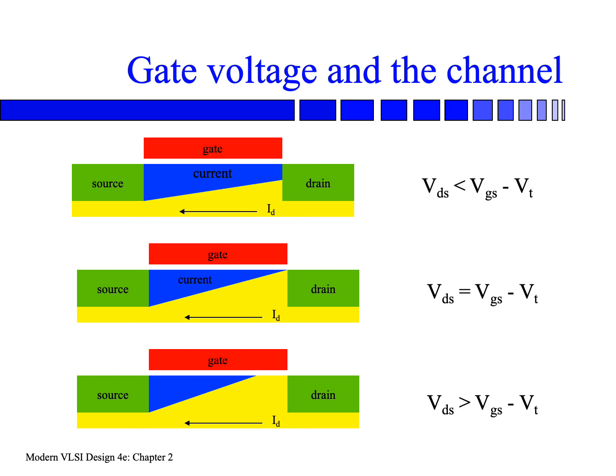But if we continue to increase the drain voltage, then pinch-off will happen. Essentially, some portion of the channel has no channel anymore. But magically, there's still current flow because there's a very large voltage between the source and the drain, since you continue to increase the voltage at the drain. So the voltage difference between the source and the drain keeps increasing, and magically they can still get the charge moving from the source to the drain.